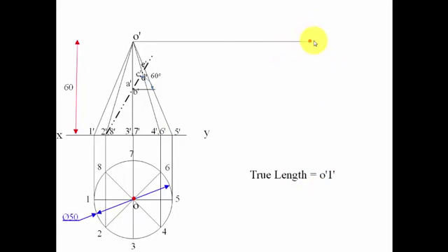Let's have a point, big and bold, O point, and with O dash 1 dash as the radius and with this point O as the center, I'm going to put up an arc over here, something like this. This angle is going to be, guys, 138.5 as we have already calculated. On flattening up the cone, the angle it is going to subtend at the center or at the apex is going to be 138.5. Fine, let's move ahead, and this is going to be the overall pi.